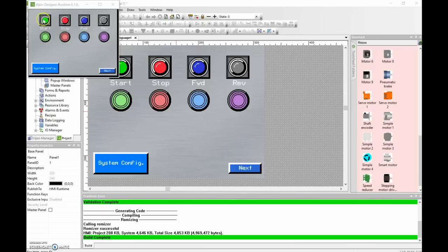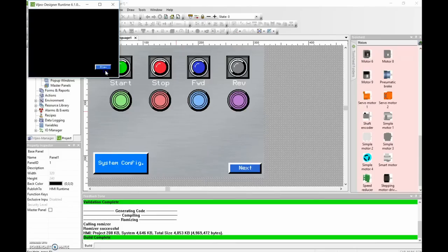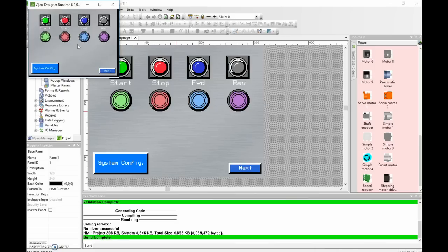There we go. So by pressing any of the push buttons, then the light below is going to turn on. Eventually we will figure out the configuration to send that signal into the PLC. We're also going to place another button down here so we can add in different additional windows with other push buttons if we want. And as I learned the hard way, if you lose the IP on these guys, it's very hard to get back to your system configuration.